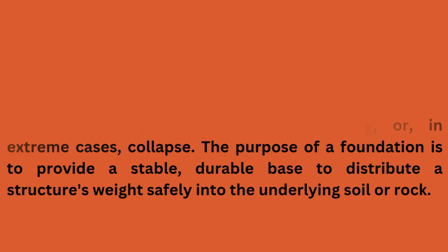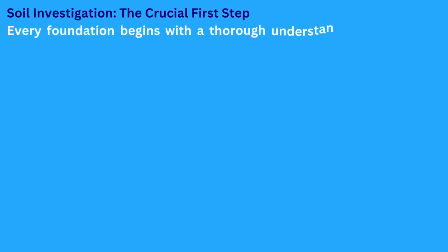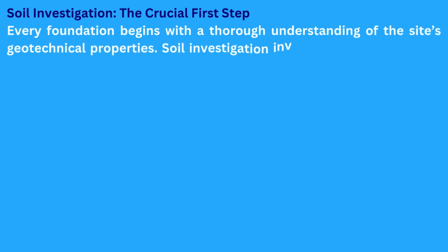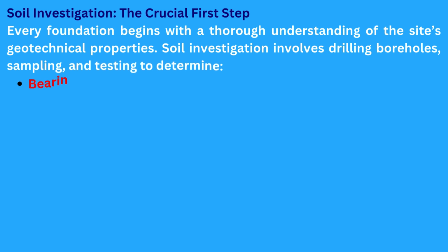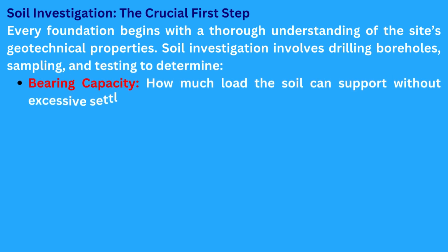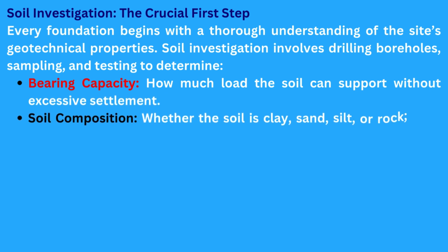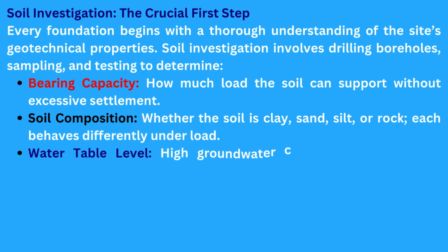underlying soil or rock. Soil investigation, the crucial first step. Every foundation begins with a thorough understanding of the site's geotechnical properties. Soil investigation involves drilling boreholes, sampling, and testing to determine bearing capacity, how much load the soil can support without excessive settlement. Soil composition, whether the soil is clay, sand, silt, or rock, each behaves differently under load.